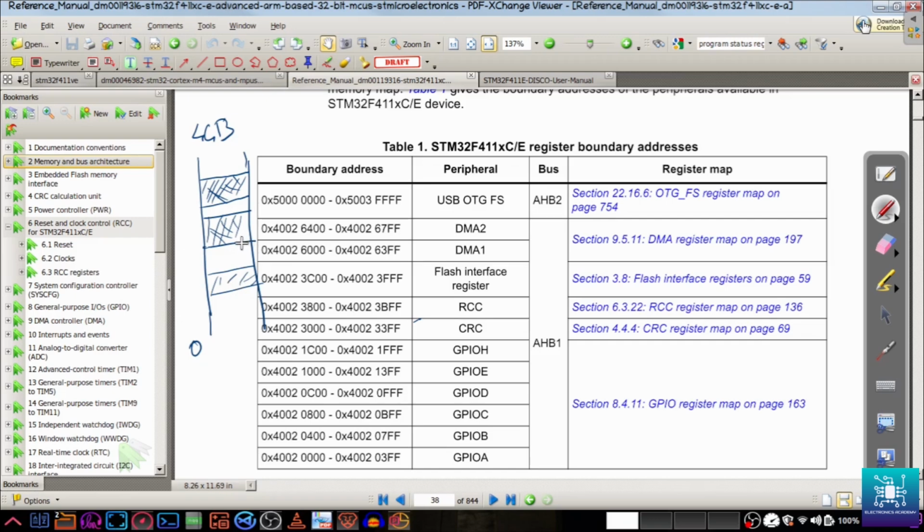For example, for the peripherals, the lower and the higher boundaries have to be at a particular memory location, and then the vendors can move things around. For example, for TI controllers, the flash starts from memory location 0, but in the case of STM, the flash starts from memory location 0x08000000. That is where your code memory is put, and the ST microcontroller starts accessing the flash memory from that location. There will be differences like that between microcontrollers, which is acceptable.